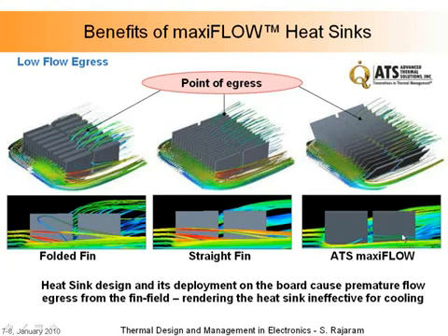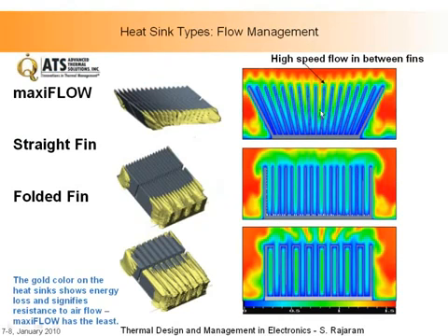So these are some additional parameters that you get when you do the CFD analysis, because you can actually see from flow analysis that you are in fact forcing the flow to go inside the fins, whereas in these, the flow is separating. So CFD is a very, very important and critical tool for our analysis because it gives us extremely good qualitative information, which we then take through testing, through measurements.